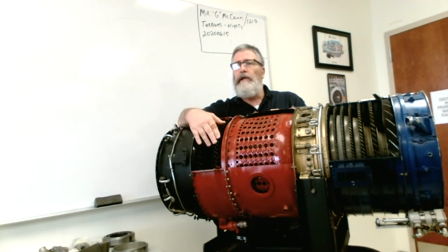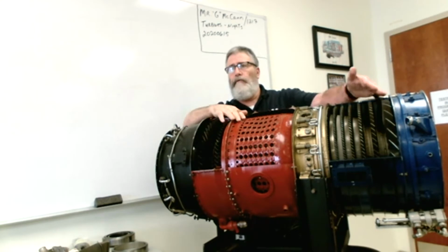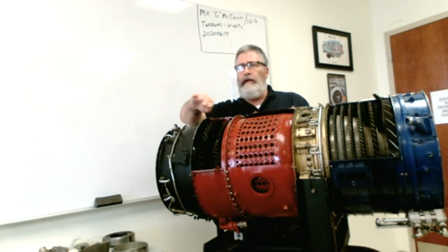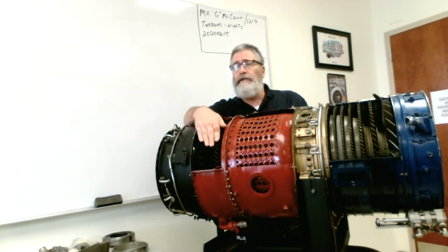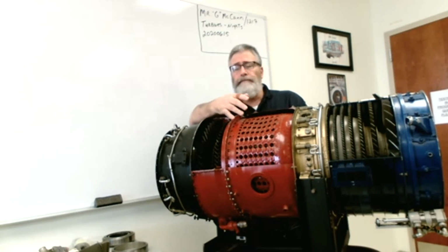The pilot catches it. Basically, he would turn the fuel off, he would hit the starter button, and he would just simply rotate the compressor to blow air through here to help evaporate and blow out that residual fuel, right? If he did not do that, and he got back into the aircraft and there was a pool of unburned fuel in this combustion chamber, then the next start could very well be a hot start.